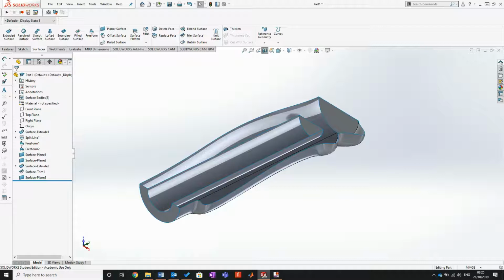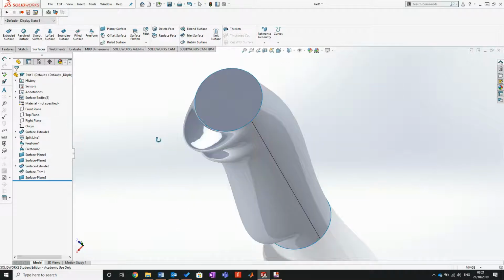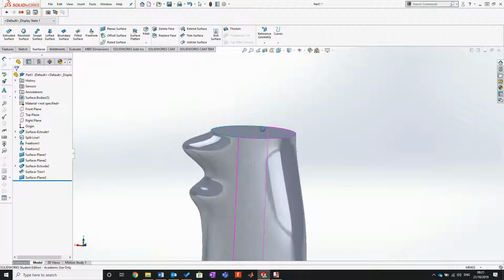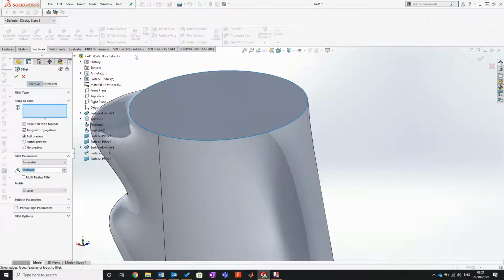This technique is phenomenal for doing all different types of things. I realised as well, after some said you put a face fillet on and a knit, ideally you wouldn't really use a face fillet after a knit. This is just my mistake. Apologies from that end. I will fix that. But if I go to 1 second, you see I've not knitted because I want to show you what I was talking about. So I'm going to go fillet,